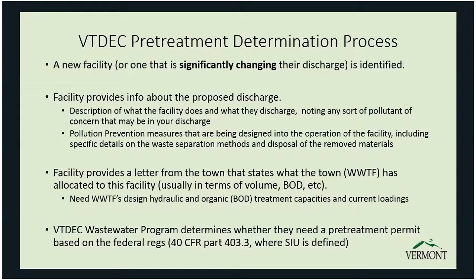The facility also must consult with the town to receive an allocation from the town in terms of what the wastewater treatment plant can handle. And we would, of course, use the wastewater treatment plant's design, hydraulic and BOD treatment capacity and their current loadings to determine the impact of your discharge on that plant.